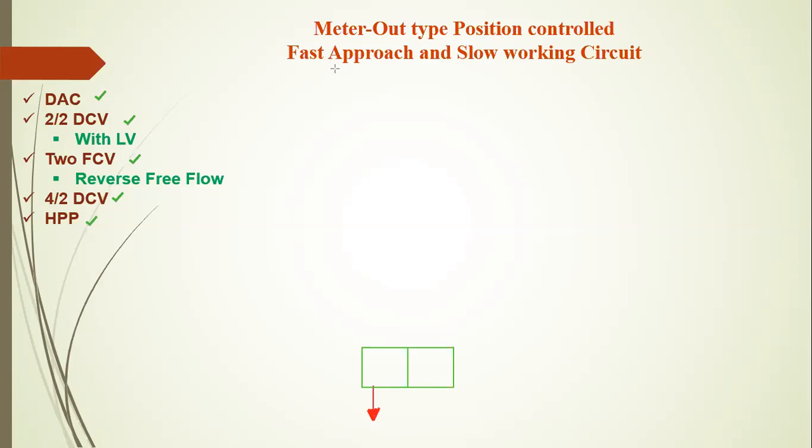For position 1, draw parallel in and parallel out, and for the other side draw cross in and cross out. Always remember to give the operating condition on both sides of a direction control valve. Here I give one side manual operated, and the other side operated by spring.